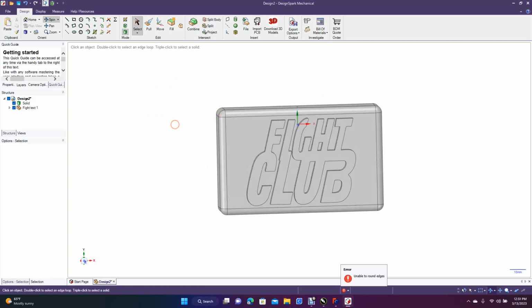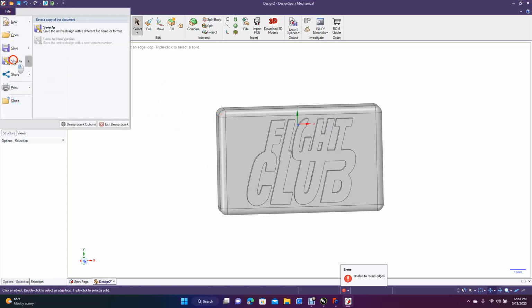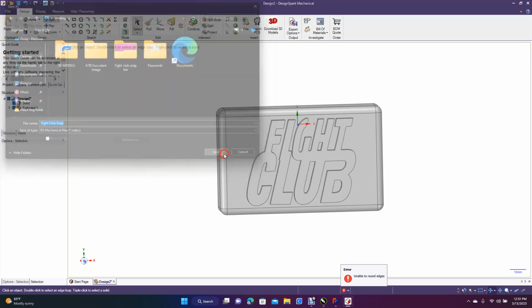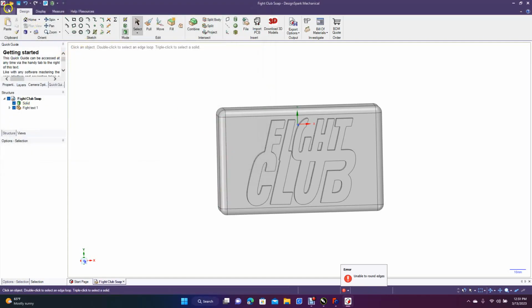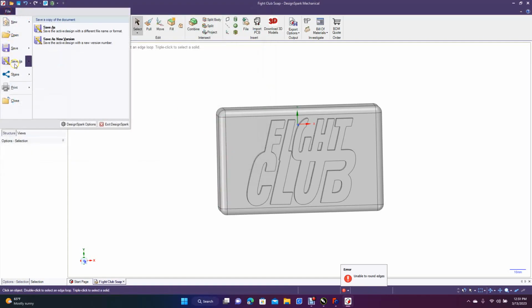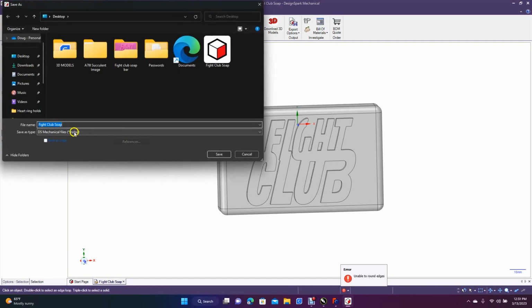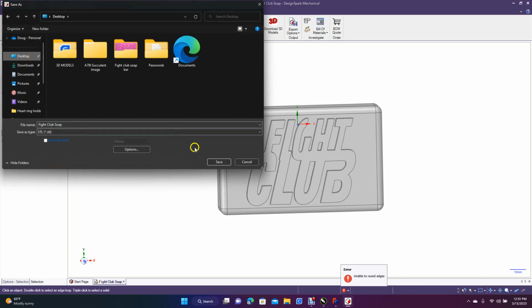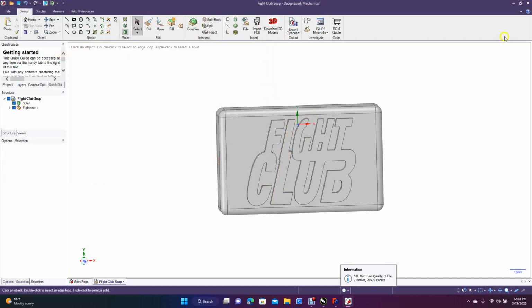So what we're going to do now is save it. I'll do a save as. We'll save the model, so we'll call this Fight Club Soap. Okay, so we'll go to desktop. We're going to go ahead and save that. And then we're going to come up here to File and do a Save As again. And we're going to change this type down to STL. We'll save it as an STL file. Go ahead and save.